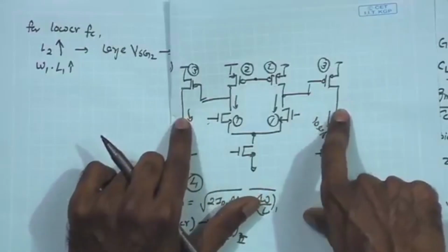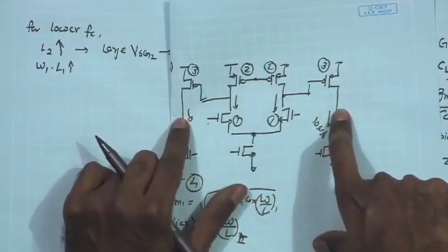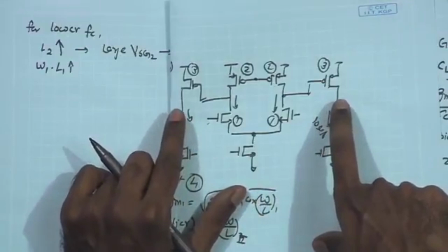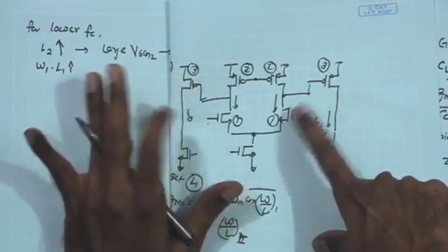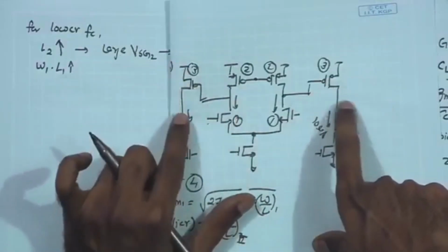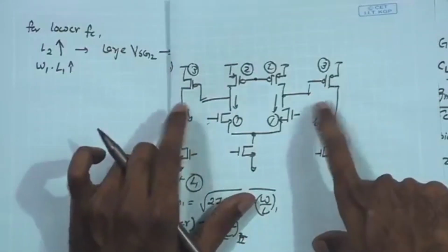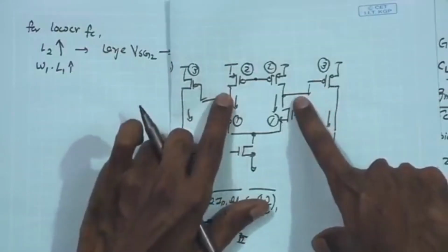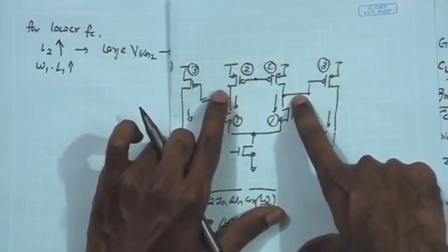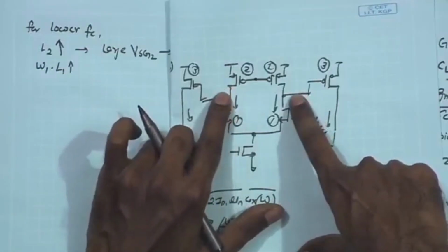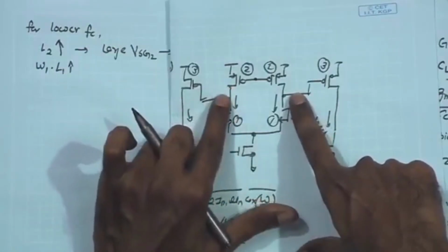With a closed loop gain of 100, the amplifier at the output will be producing 100 micro times 100, and for that 10 millivolt the input swing over here will be further 10 divided by 100, so 0.1 millivolt. Therefore, the swing over here may not be a serious constraint.